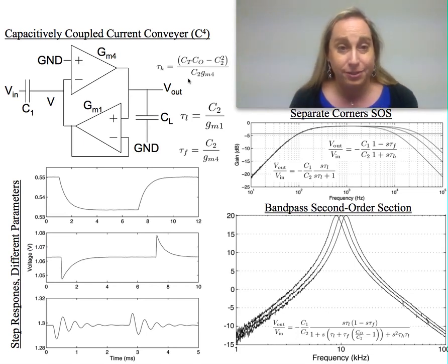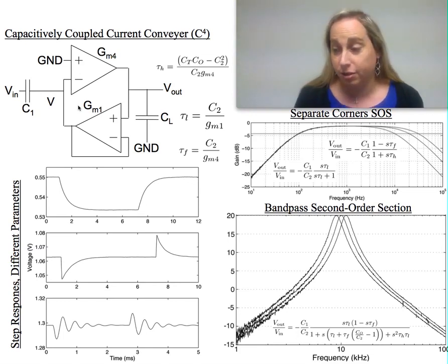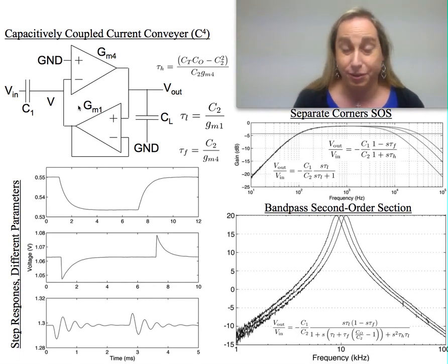As a result, you can utilize this structure, particularly if I'm using C1 as sensor elements, I can utilize all the capacitors to some advantage. Now, if these OTAs are reasonably ideal OTAs, then you really only have two poles in the structure. So you actually have two state variables, one pole, one zero, one sort of pole zero, that come out of the structure.